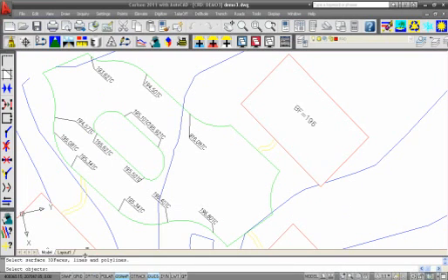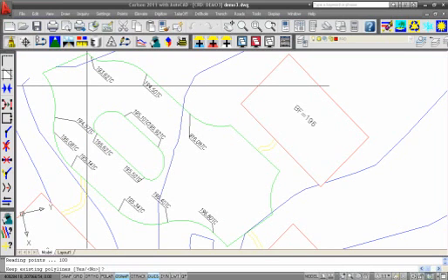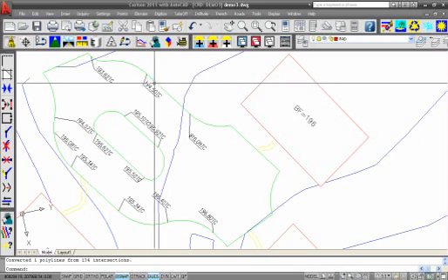And select the 3D faces, lines, or polylines to elevate it by. So I could type in all and select all the contours. I'm just going to click on the 3 that are close by. So I have 3 contour lines here selected. I'm going to hit enter. Keep existing polyline, I'm going to say no. And change the layer, no, I don't need to. And it says converted 1 polyline.